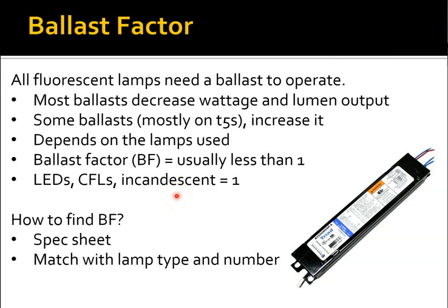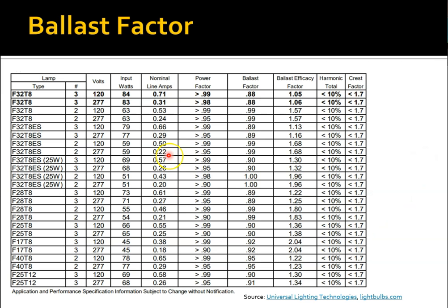So let's do that. I looked up a ballast, and to make sure it's compatible, it actually takes a little bit, sometimes a lot, of investigation to find a ballast that's compatible with your lamp. And so I did find one. What I did for this is I went to a vendor online, found my lamp, and a lot of times they'll say it's compatible with this ballast or this and this and this, right? And so I found that, and here's part of the spec sheet from that ballast.